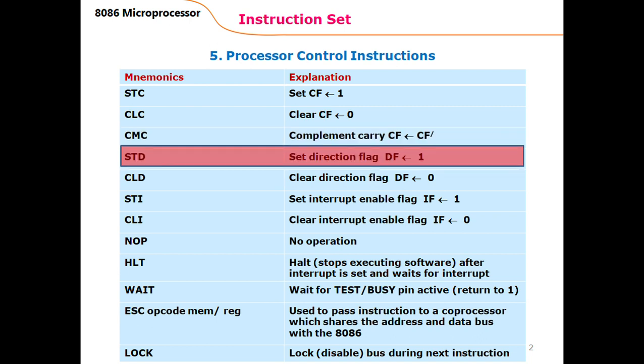There is another important flag bit in the flags register called direction flag, normally represented with DF, or in certain books it is represented with D. So DF means direction flag. Direction flag is a very important flag, in particular used in string manipulation instructions. The value of this flag sets auto increment mode when the value of D is 0, or auto decrement mode when the value of D is 1. So it sets the auto increment or auto decrement mode used during the string manipulation instructions.